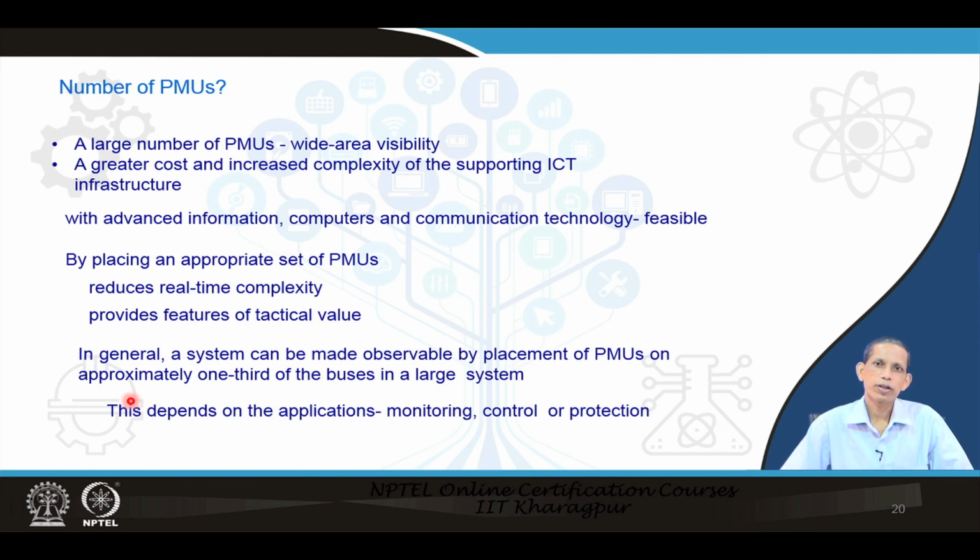The other important factor is how many PMUs are in a system for a particular application. More and more PMUs means that the visibility will be better, and you can see more insight into the system behavior also, but this has a greater cost associated, and increased complexity in handling the data and the ICT infrastructure. With advancement in information technology, computers and communication technology, such a voluminous data platform is feasible today.